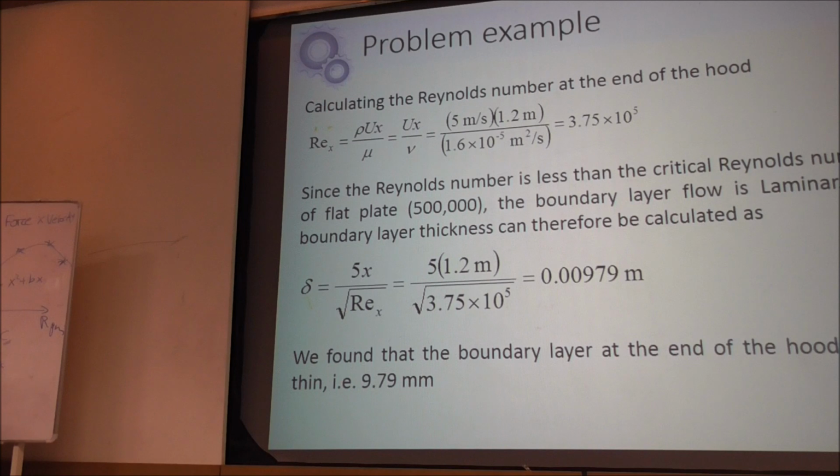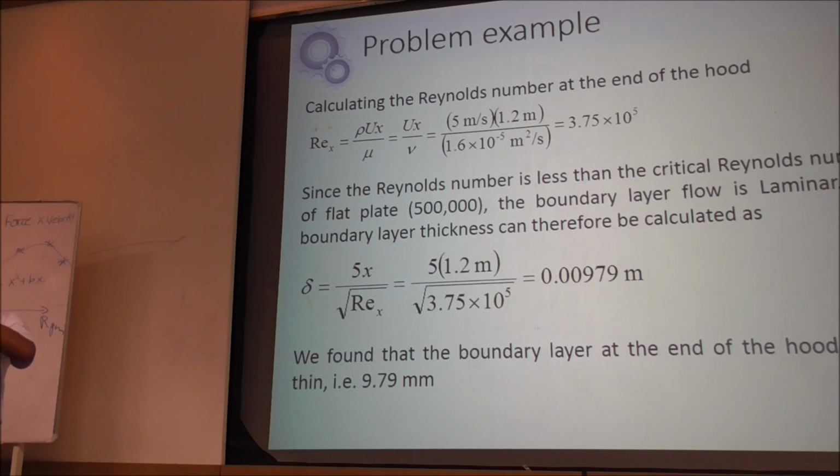So basically, in this external flow, you will know how much power is needed to overcome the fluid friction. If you can calculate the friction exerted by the tire, so if you combine dynamics and fluid mechanics, you can design how much power is needed to drive your car. Because you know the rolling friction, once you calculate the rolling friction, you calculate the air friction. You combine those, you will get the power needed to propel your car.